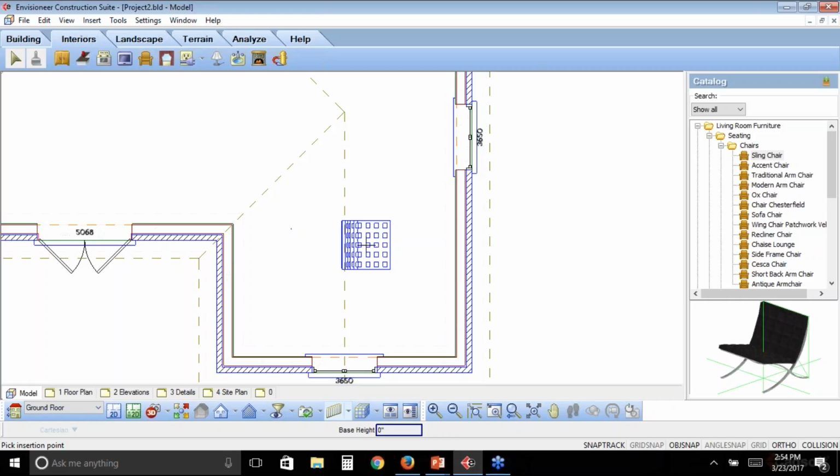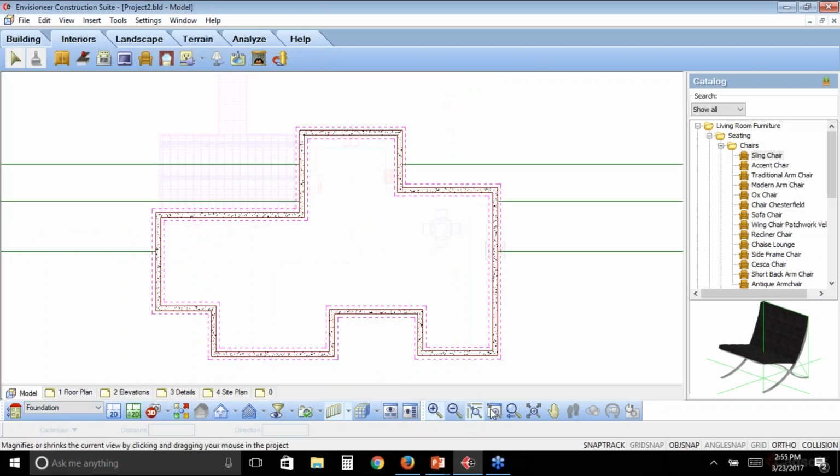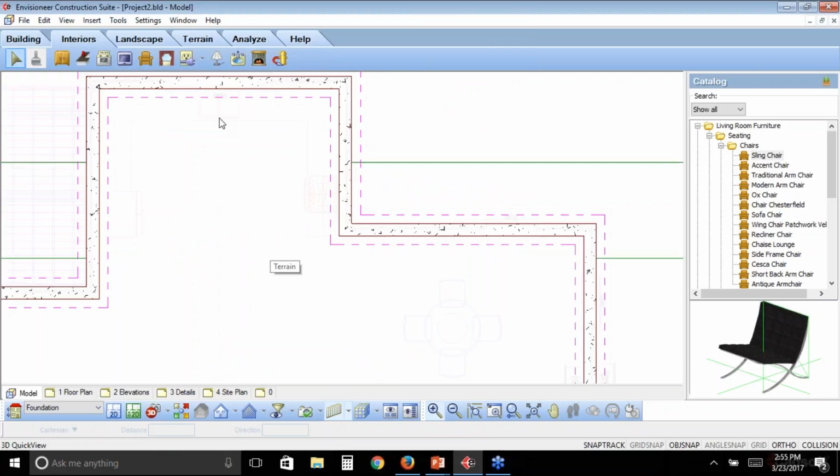And when you start cutting sections and looking in 3D views, that's when you're going to see potential errors of the different information. So as another example, I'm going to go down to my foundation plan. In my foundation plan, I'm going to zoom in close so you can see it a little bit better. Depending on your computer, you may be able to see the lightly ghosted objects on my ground floor. You can draw up to 999 stories in our software. And as you're drawing all of those various locations, you'll be able to see lightly ghosted how they're going to be situated. So I can see my sink here, and I could put in a beam and all my different elements, and then I could